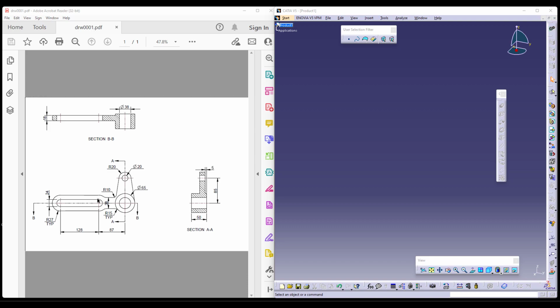Since this particular portion and this has the same addition of material which is 18, we will make this circle first and then proceed with the remaining portion of our body, of our lever at least. Later on we will start removing or drilling our holes which are 20 dia holes and removing our slots as well. Now, continuing with the model, we are using CATIA as the CAD tool.